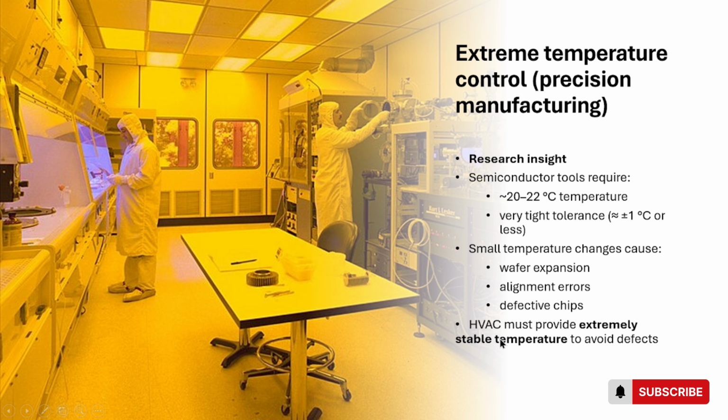So now come to the temperature requirement in a fab building. In the fab building, the temperature requirement is around 21 degrees Celsius. You can also say 20 to 22 degrees Celsius.